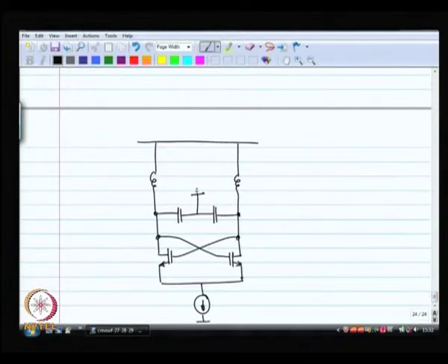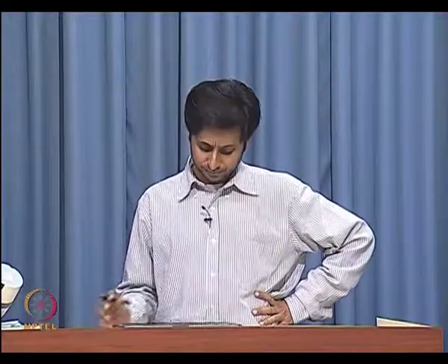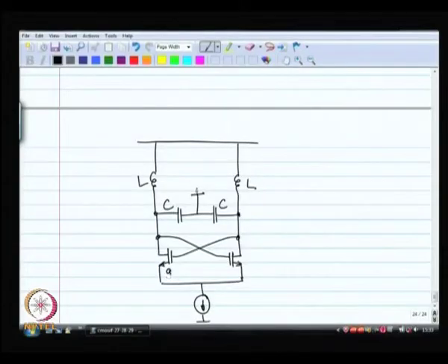So, this is my standard oscillator, all right. And let us say that both of these MOSFETs under quiescent operation have a certain amount of GM. Let us use the extremely basic small signal model of the MOSFET. There is GM and there is RDS, right. However, that is not really correct, right.